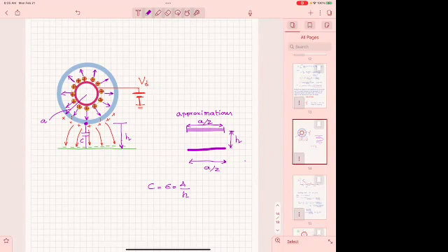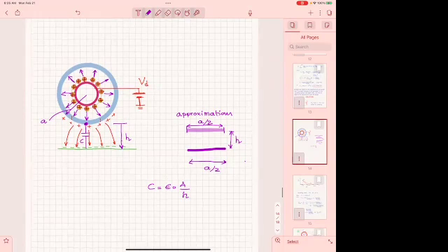The interesting thing here is that if you assume that this cylinder is a line, and usually lines, for example, when you design those lines that I show you, like an HDMI, they do not talk about the total capacitance, they talk about the capacitance per unit length. Because you never know, this HDMI, for my case, is much longer than yours. What's the point of saying I have an HDMI which is like 1 meter? Well, mine is not 1 meter, maybe it's like half. If there are cables, they never give a total capacitance, they give a capacitance per unit length, so you can translate it into whatever length you have, all right?